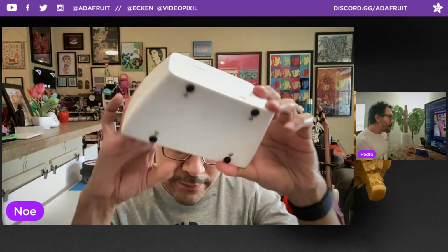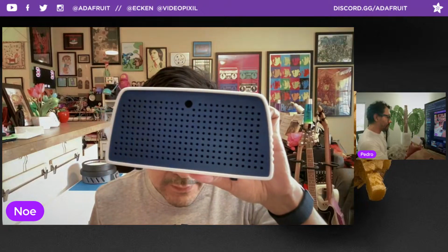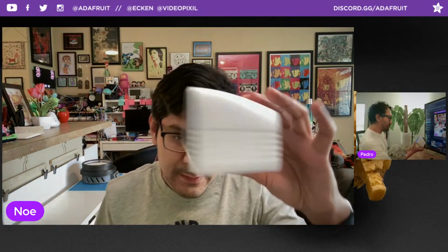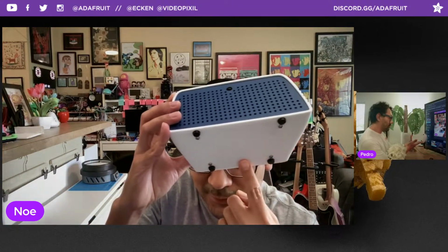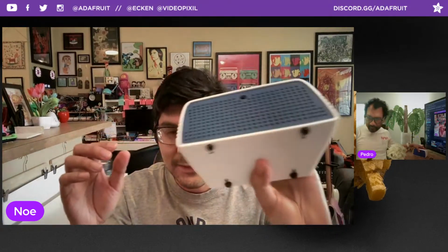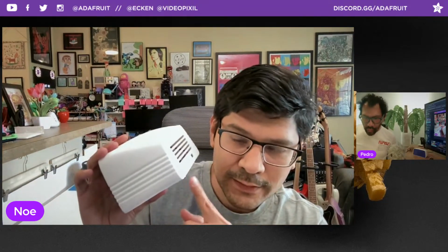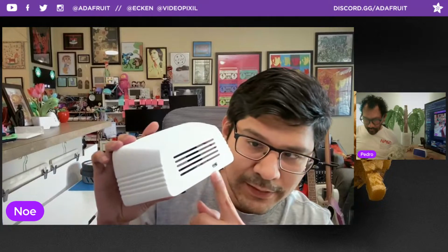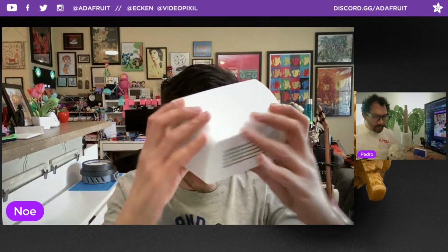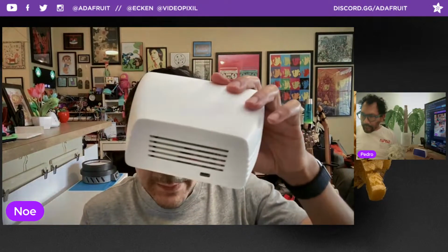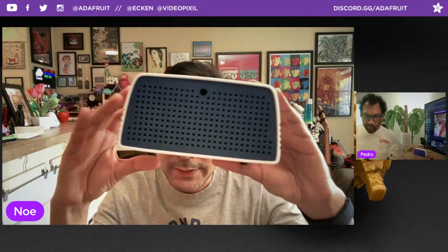Just a couple screws here to mount the PCB mounting plate that houses the 2 boards and the speaker. And it's modular. So if folks want to put in their own $1 ESP board, they totally can. Why not? So you can remix it. If you want to make it battery powered, the feather is a great choice because you just plug in one of the compatible batteries, and then you can have a slide switch back here, and then you can have it portable if you want. But we'd like it to be simple and easily approachable, and powering it with the USB is probably the easiest way to go.